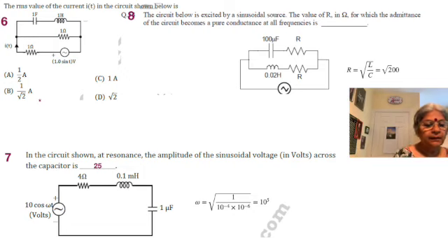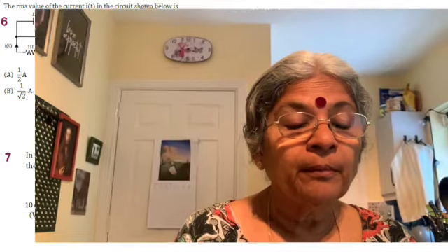And then what is the current? Because it's a pure resistance now due to resonance, 10 divided by 4 is going to be 2.5. 2.5 maximum value is going to flow through the inductor or the capacitor, creating the same voltage. So it's easier to multiply, 25. Okay, let's go to a different kind of situation altogether.